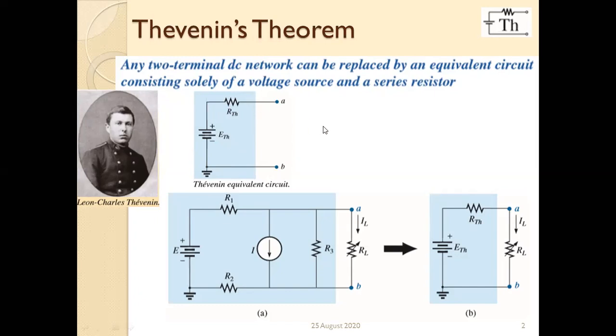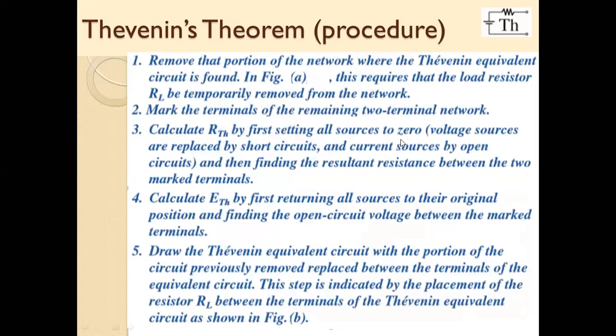Now, Thevenin is saying that if you replace this circuit by this circuit, it will not affect the output characteristic of the network. That is, if you again attach the external part of the network to this small network, then the values of current, voltage and resistance between these two terminals will remain the same. So that is the Thevenin equivalent network, or the Thevenin theorem.